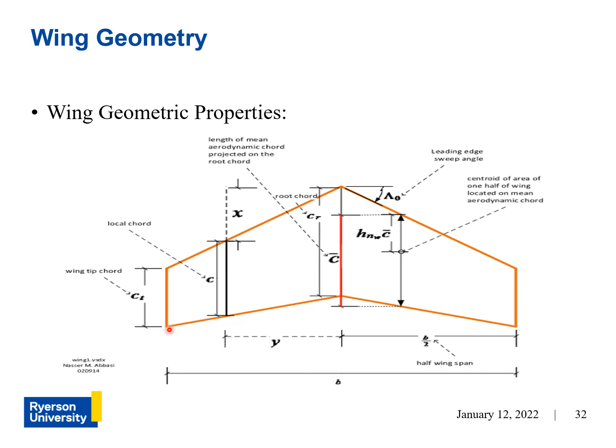The reference wing is a fictitious wing that extends through the fuselage to the aircraft center line. So in a real aircraft, the fuselage would be somewhere here, and this reference wing just extends right into the center line of the aircraft.